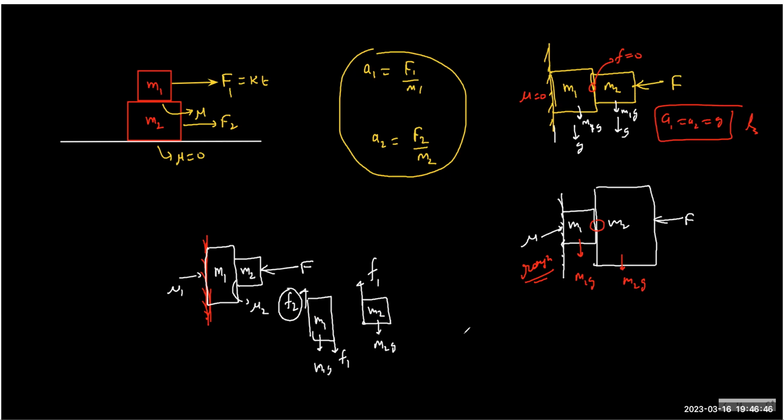So what will we check? Is F2 max more than M1g plus F1 max? Answer, yes. A1 is 0. If F2 max is more than or even equal to this value, it means M1 will always be balanced. So A1 is 0. Then you can go to M2.